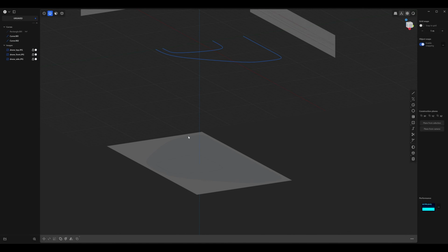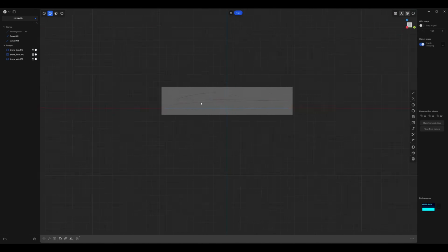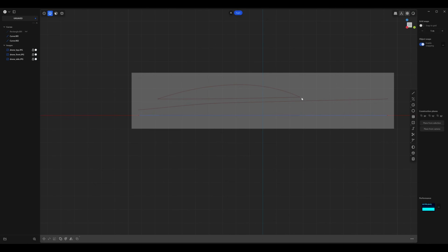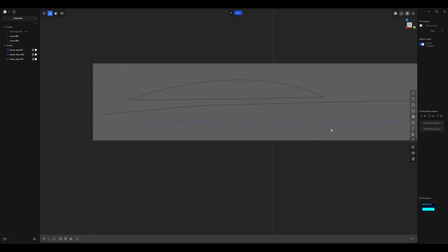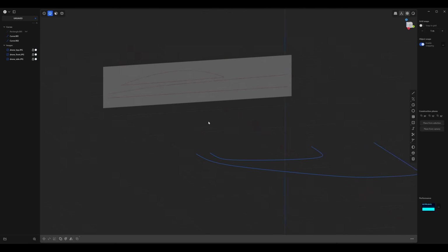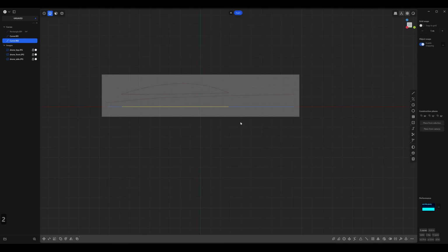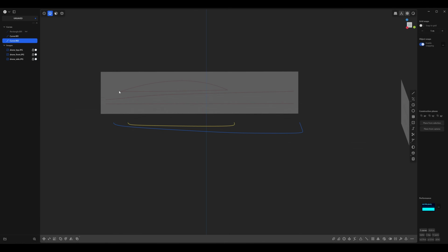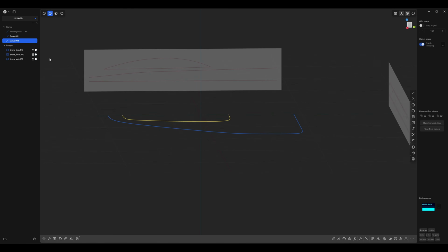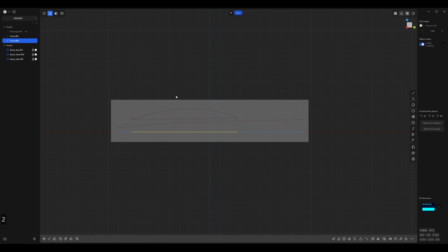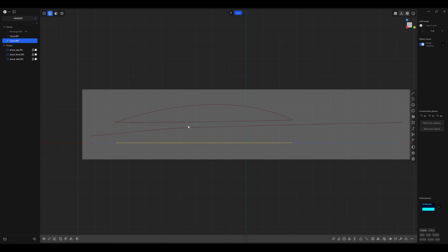Next, we're going to go to the right side, and we're going to design this top canopy area. In the perspective view, you can see that our canopy is just on the same level as our bottom line of this drone. And it's actually up here, so make sure you select it in perspective or in your outliner. And then let's go to the side view and let's move it up. So press G and move it up the Z-axis.